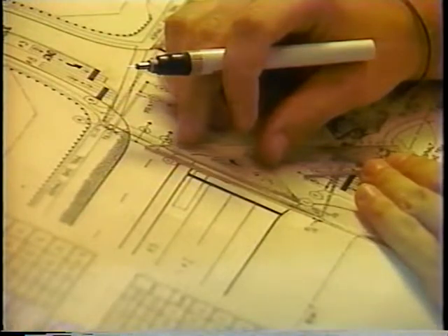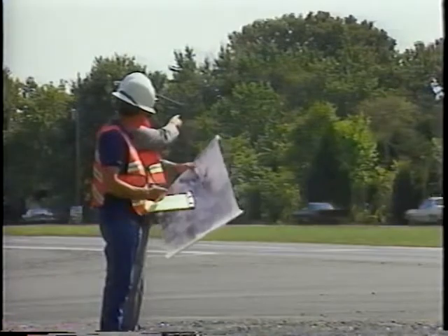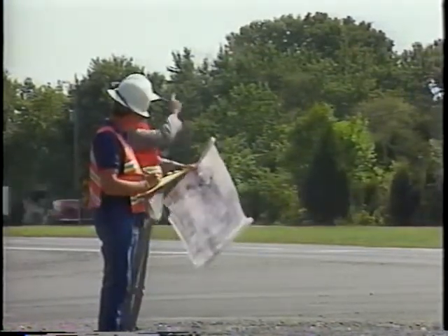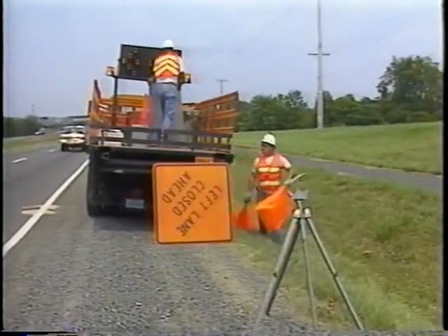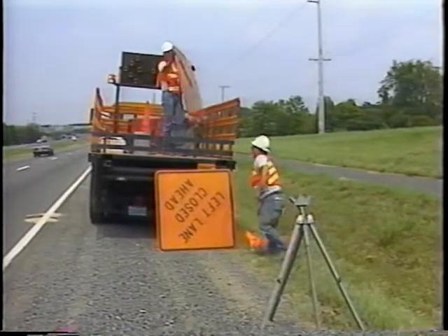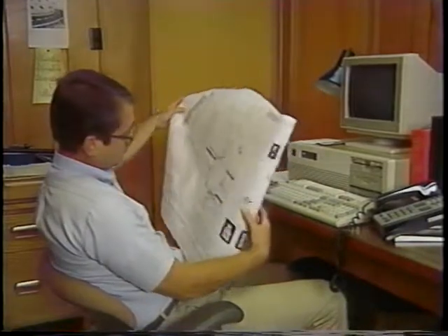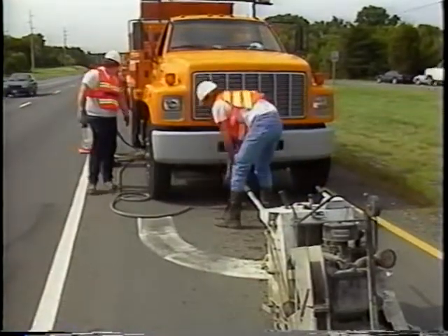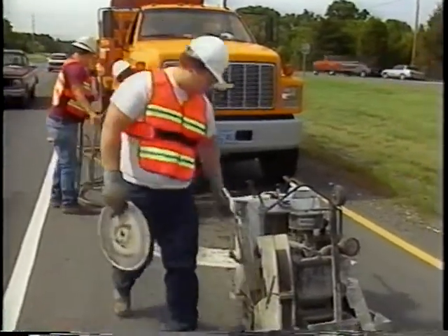The information obtained from this initial visit is then incorporated into the plan drawings. A second field visit should be made to verify the accuracy of the completed drawings. If the installation is to be performed by an in-house crew, the next step is the estimation of manpower requirements. Studying the plans, determine the scope of the installation work, the amount of time required, and the size of the crew. Often, a crew should perform certain installation tasks simultaneously to reduce the time that traffic is disrupted.